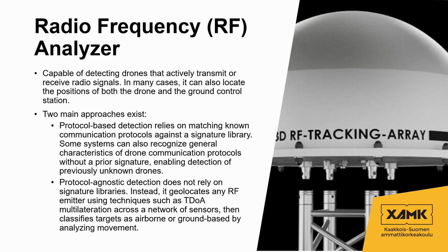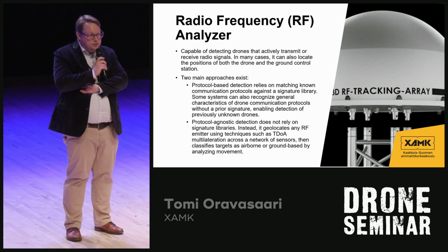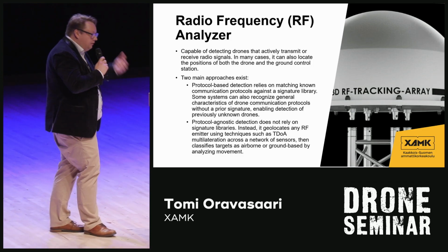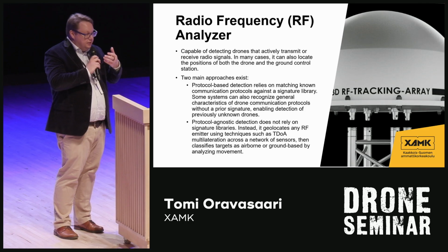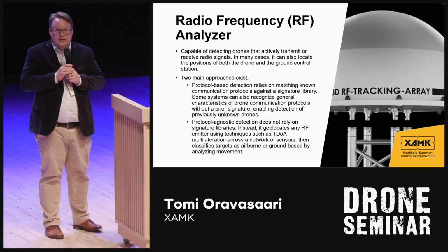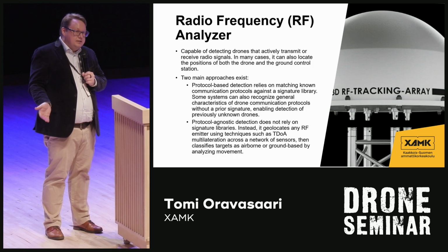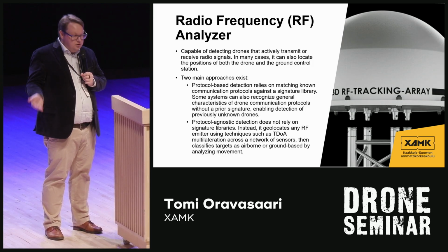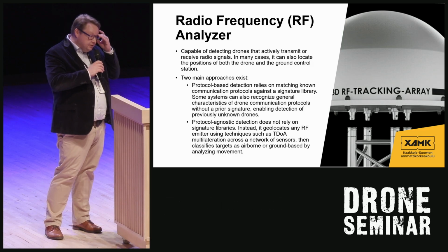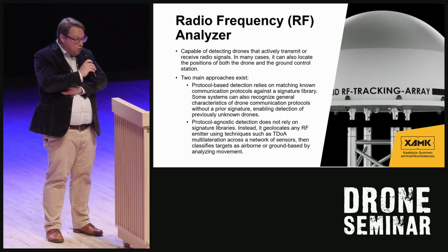You can use a signature library. These manufacturers have recorded what kind of radio signature different kinds of drones transmit. When the analyzer detects a radio transmission, it compares it to the library and decides whether this is a drone and what kind of drone it is. I think this is the most used method for radio frequency analyzers to detect drones.